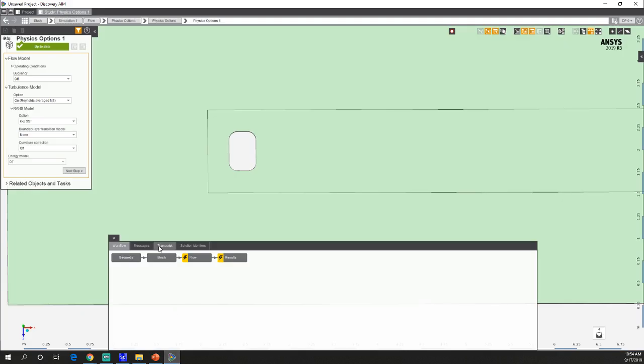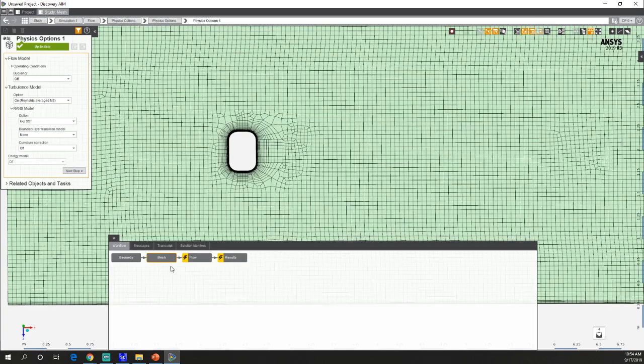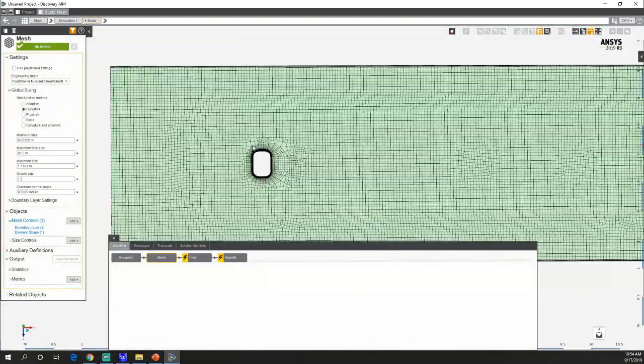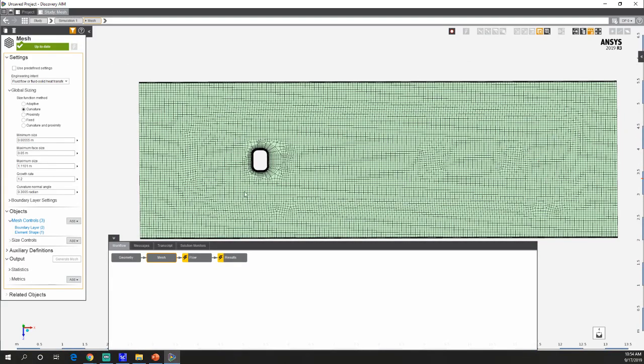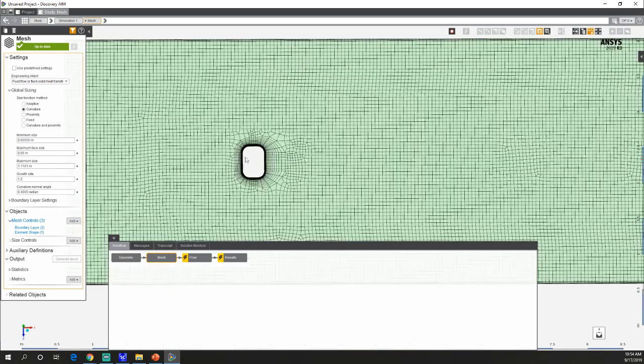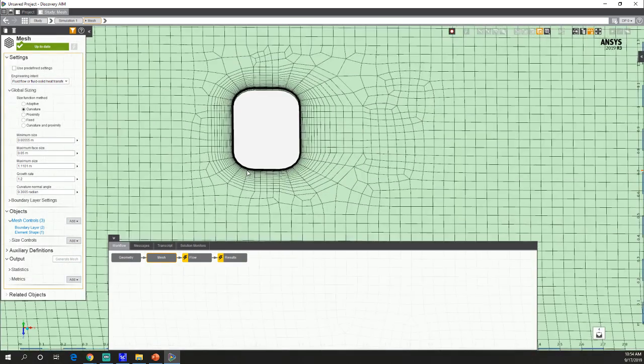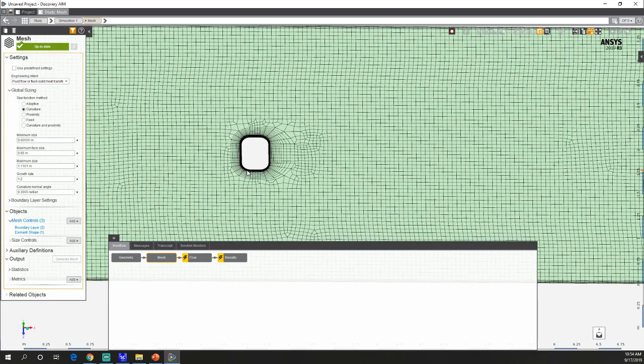Some of the key things we learned today is to manually control the meshing so you can refine the mesh near the structure. Try to refine the wake region. I had some issues at the end, but we can sort that out easily if you decide to try that. So refine the wake region. Don't rely on the default setting for these types of pseudo 2D models. Even for 3D models, meshing is really important, right? Before, having a boundary layer mesh versus not having one would change your results by 10, 15, 20%. So having a good mesh is important.